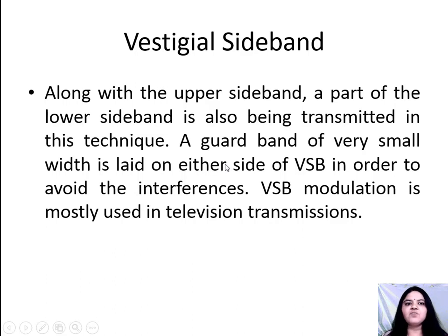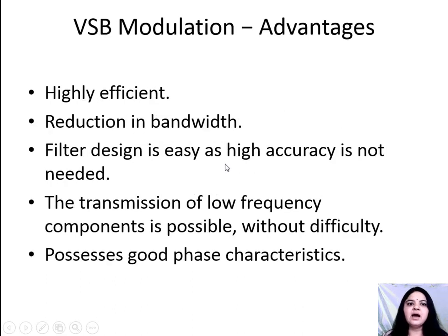The advantages of VSB modulation are: it is highly efficient, there is a reduction in bandwidth, filter design is easy as high accuracy is not needed, the transmission of low frequency components is possible without difficulty, and it possesses good phase characteristics.